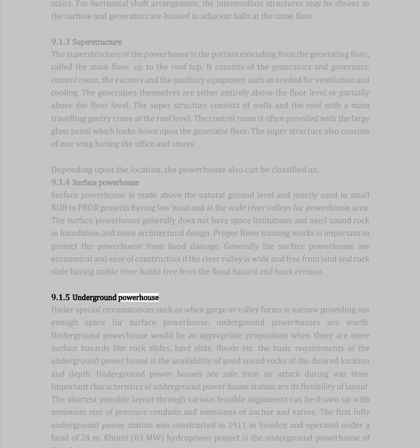9.1.5 Underground powerhouse. Under special circumstances such as when gorge or valley forms is narrow, providing not enough space for surface powerhouse, underground powerhouses are worth. Underground powerhouse would be an appropriate proposition when there are more surface hazards like rock slides, landslide, floods, etc. The basic requirements of the underground powerhouse is the availability of good sound rocks at the desired location and depth.